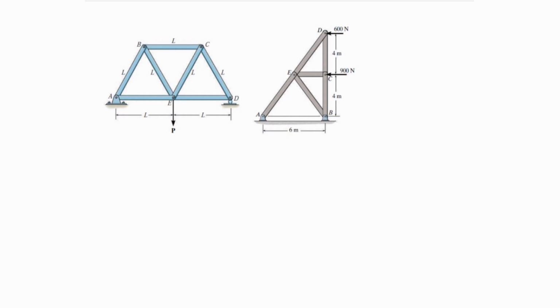One of the main questions that we are facing is where to start. As we discussed before, the first step in solving the trusses is finding the zero force members, and then after that it could be a free body diagram of the whole system.